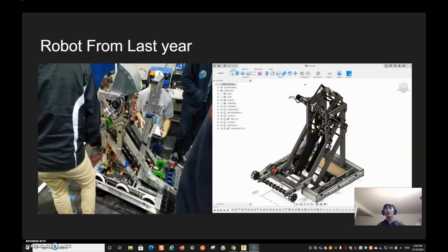Now, the purpose of a shooting hood is to guide and compress the ball. The ball needs compression to travel far. Otherwise, if you don't compress the ball, it's just going to roll up and out of the shooter. If you have the flywheel fast enough, it might go some distance like ours did. But essentially what it did was limit our robot's shooting range to about 3 feet, which meant that our robot did not have a lot of versatility, and so this shooting hood was basically useless, so we will try to replace it with this one this year.